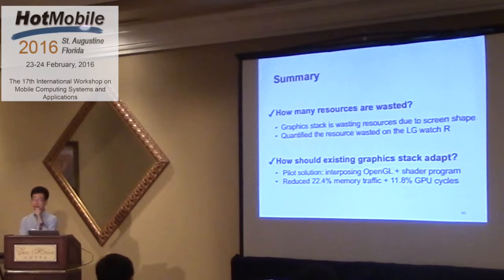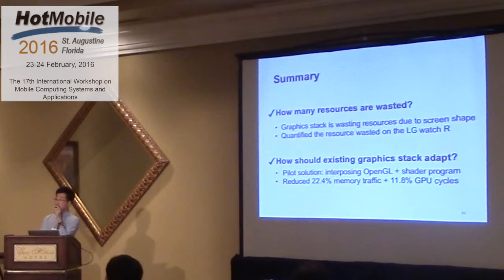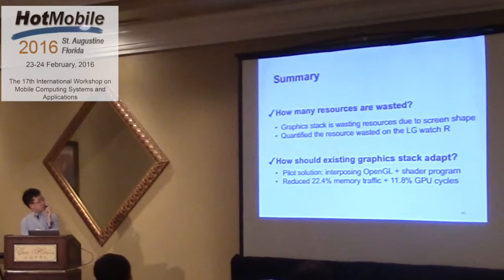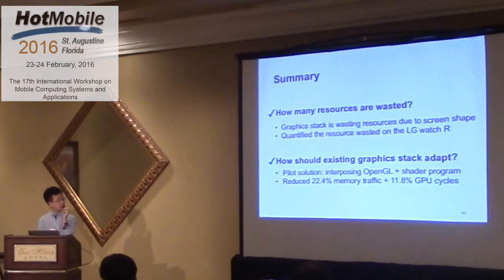So let's summarize what I have done. For this work, there are two top questions. For the first question, we have proved that the graphics stack is wasting resources due to the screen shape, and we quantified the resource waste on the LG Watch R. For the second question, we propose a pilot solution where we interpose OpenGL commands and rewrite the shader program. And our method can save about 20% memory traffic and 11% GPU cycles.